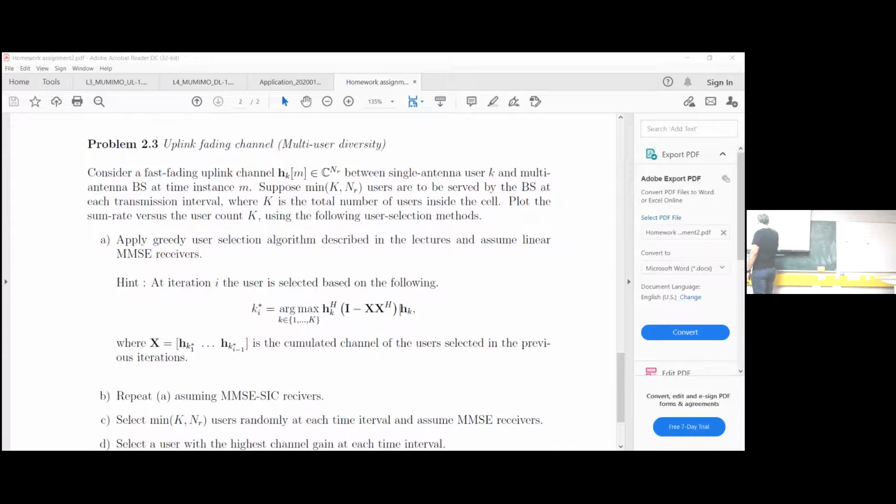Okay. So from the user K perspective, we have the desired signal, and then we split the interference into 2 parts, right? Assuming this encoding order from K to 1, these indices I that are larger than K can be assumed as side information because those are already designed.